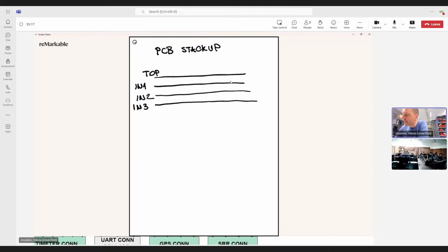Yes, but in this scenario, for example, we would have a strip line structure which is confined between two ground layers. So the field will be confined here. That's true. But what happens here with the transition of layers? This will generate common mode currents because we switch the layers, and the return path of this signal is not, let's say, so straightforward.